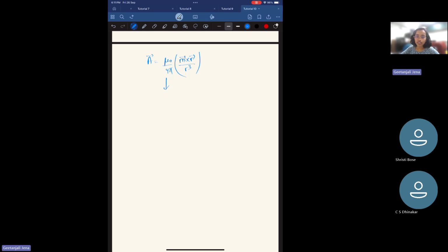If you recall the electric field case, we have the dielectric. If you put in a dielectric, there will be separation of charges, so we see volume bound charge density and surface bound charge density. Similar to that, here we have bound volume current density as well as surface bound current density.